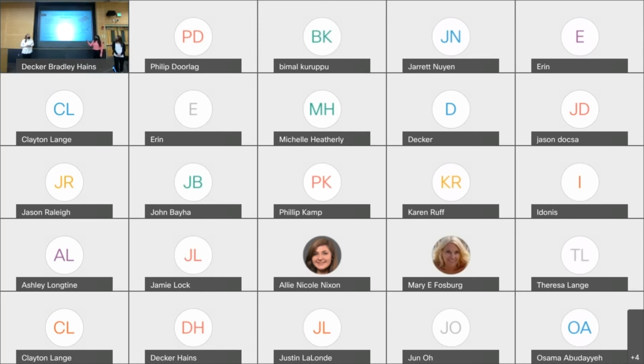So one of the assumptions was that the wind acting on this frame, we took it as a vertical load because it's an open frame. So we used the dead and wind load that was given by the sponsor. Those are the only loads acting on this frame. And we used it as a vertical load for the frame. However, we did consider moment when designing the concrete footing. But for the frame, one of the main assumptions was that the wind was not transverse but rather horizontal.